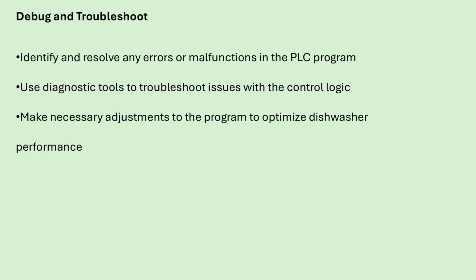Debug and troubleshoot. Identify errors. If the dishwasher doesn't operate as expected, use PLC diagnostic tools to monitor inputs and outputs. Check for signals from sensors and verify if the control logic activates the correct outputs.